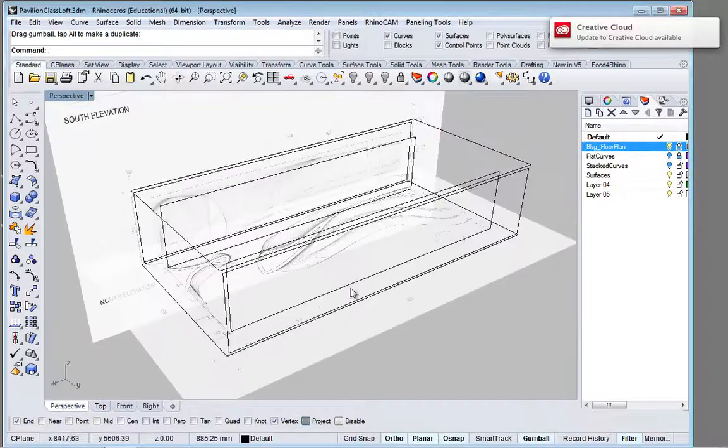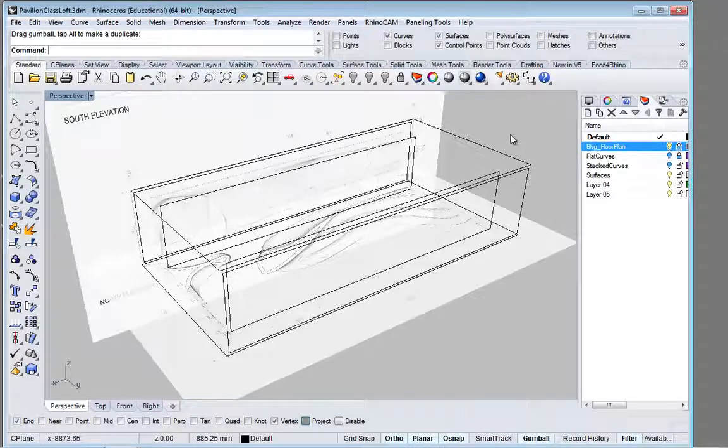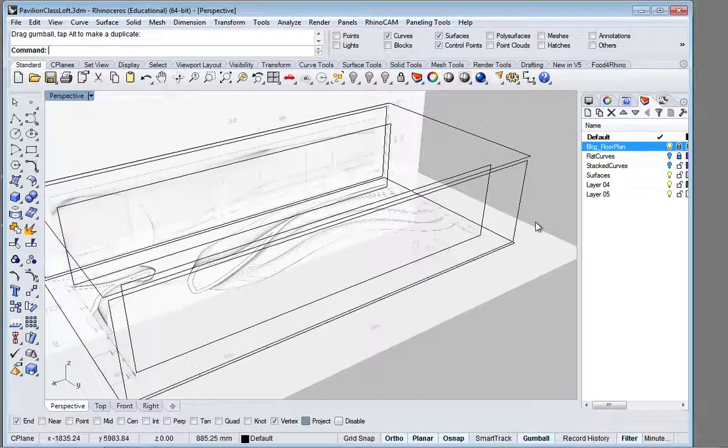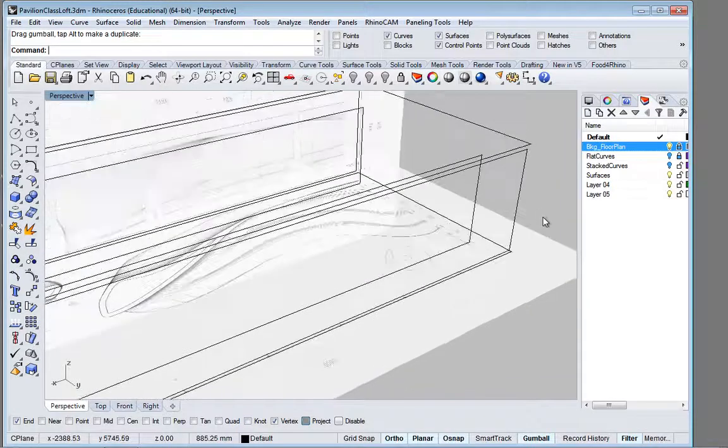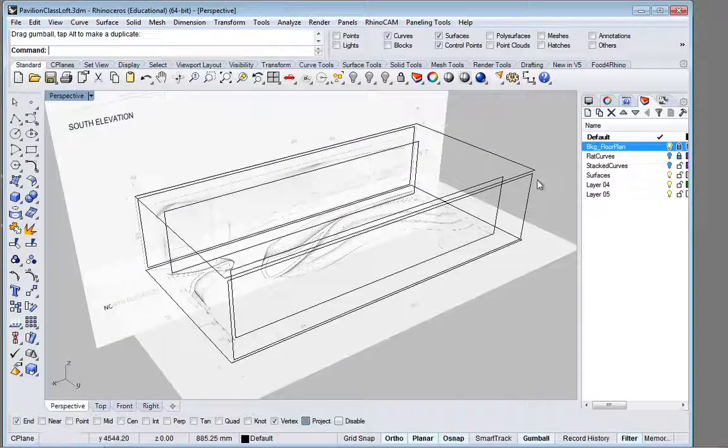Okay. So now we have this perspective view, and now I can do some modeling with surfaces. So this is kind of the base point that I start from. One other thing I'm going to do is I see that I did this top and bottom, but I want this outside edge here as well to create this surface. So I'm going to go ahead and create another rectangle using the snap.